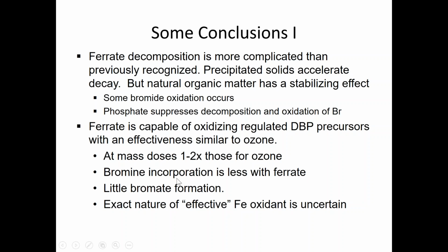Bromine incorporation does occur, and you do get a little bit of formation of brominated byproducts when you have ferrate, but it's far less with ferrate than it is with ozone. You do get a tiny amount of bromate formation, but we have yet to see a water where that is significant so that the bromate ever exceeds the MCL of 10 micrograms per liter. So it seems that bromate is not an issue, although it is for ozone.